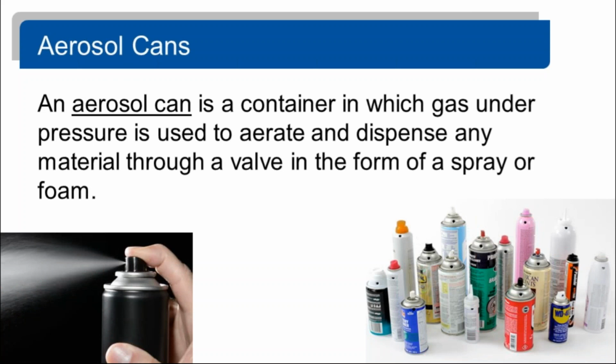Aerosol cans: a container in which a gas is under pressure, used to aerate and dispense any material through a valve in the form of a spray or foam. For aerosol cans managed as universal waste, the regulations are intended for non-empty aerosol cans. Empty aerosol cans, if they are in fact empty and not exhibiting characteristics of hazardous waste, whether reactive, ignitable or toxic, can be disposed of as scrap metal or thrown away in the garbage, but they must meet the definition of empty, which is written in the regulations as empty to normal practical extent.